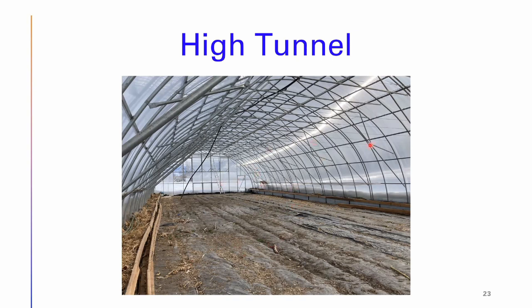The other thing I wanted to point out is if you want a cheap way to make your horizontal trussing, I used 3/16" cables here. And it's much cheaper than your tubes. I use 14 gauge. That is 1.25-inch nominal, that's 1 9/16 inch exterior diameter. Normally, when you're looking at specs for greenhouses, they'll give you the exterior diameter. So that's 1 9/16 there. But I would recommend, to minimize your loads, the tensile member is your horizontal member. Use a cable there and it'll strengthen your greenhouse significantly. Very inexpensively too.